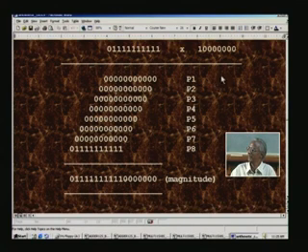That result will be added in the second stage, and naturally for 8 numbers you will have only 4 outputs, because there were only 4 adders, and those 4 outputs will be taken 2 at a time. Once again there is a second stage of addition adding 2 numbers at a time, and out comes one result, and there will be 2 such outputs, and those 2 we will add in the third stage resulting in one final sum, and all this would be registered at different points of time. In total we have 8 clocks, and therefore 8 pipeline stages inside, and hence 8 pipeline registers as well.